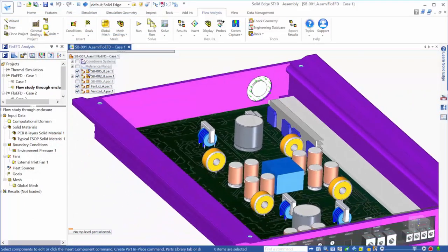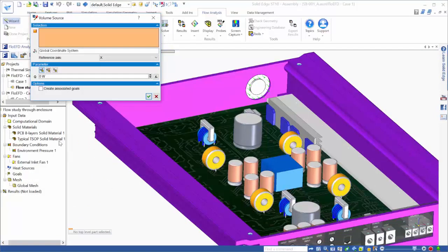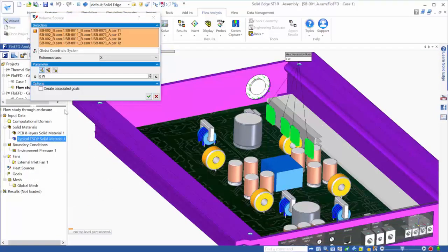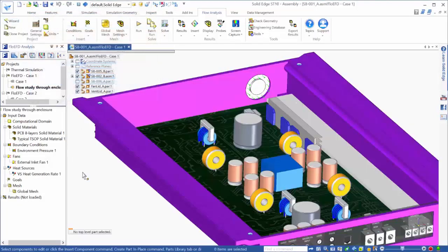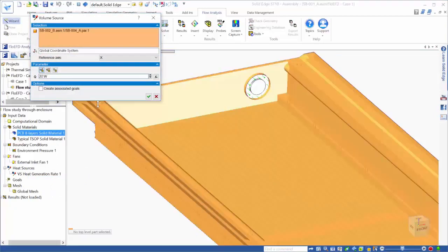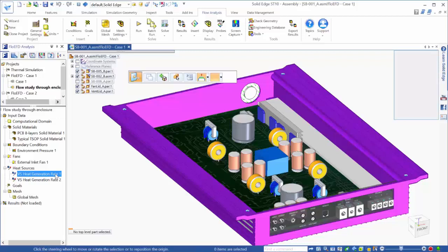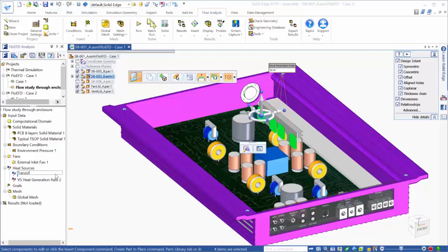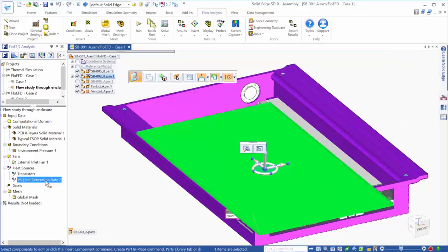In addition to how the air will flow through the casing, we also need to see how the temperature will be distributed. Our next step is to set up the sources of heat on the assembly. Once again, we'll be focusing on the PCB and transistors. FlowEFD and Solid Edge makes geometry reselection simple. As we've defined each of these components previously with specific materials, we can simply reselect that representation in the edge bar and the same geometry is automatically selected. For heat generation, the transistors will be generating 20 watts in total, with the PCB generating 220 watts.